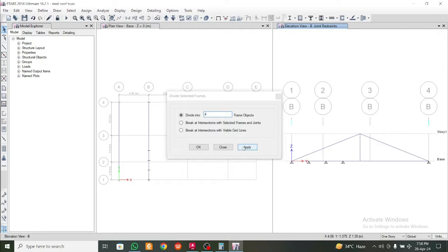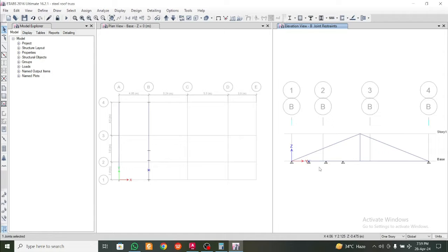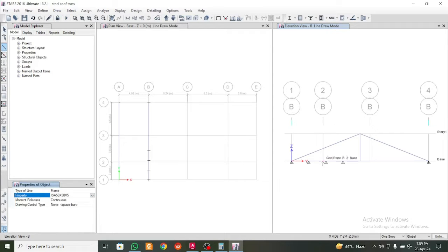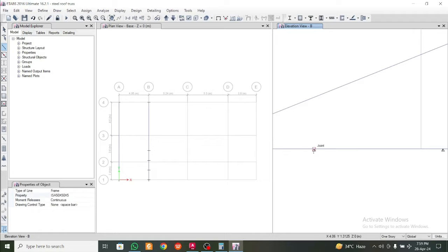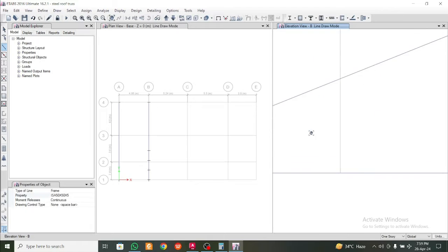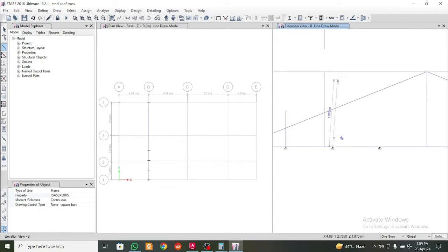then we'll have 3 vertical members, okay. So again we'll just delete this later. I can delete this later also, okay. Let it be for now. So internal member property we are planning to have 15 to 50 to 5. Same thing, just make sure you have the joint selected and you have the angle at 90 degree. Don't worry about the other things. Right click to get out of the command, select this, get 90 degrees, select left click and then right click, select this, left click, get 90 degree and left click and right click, okay.